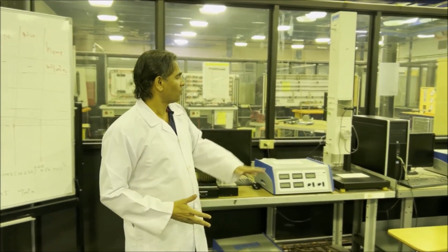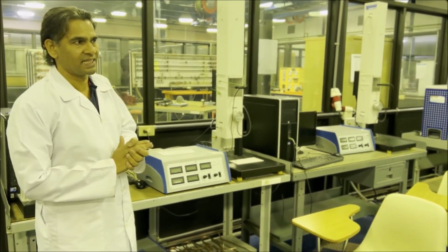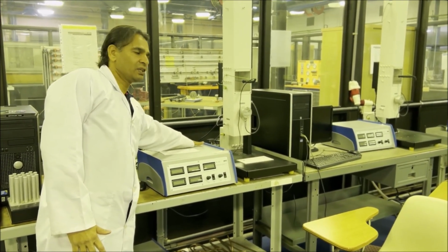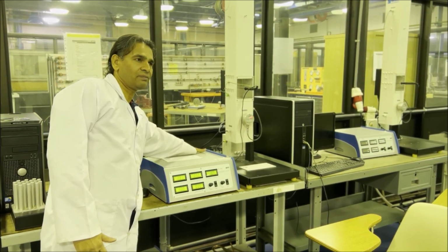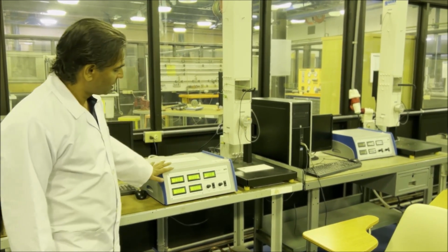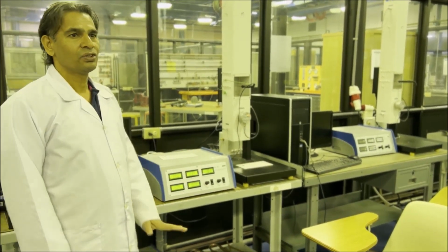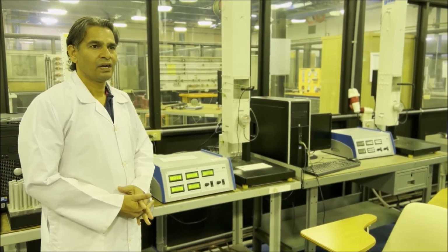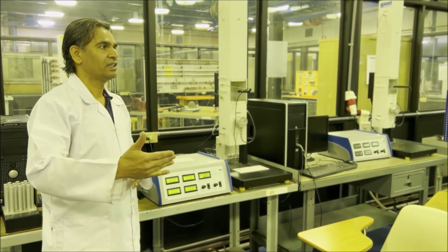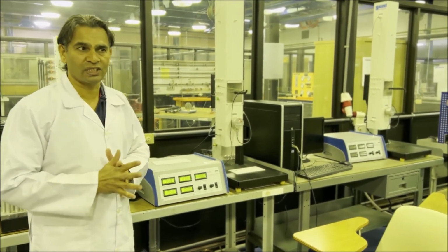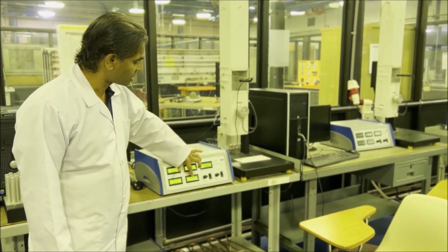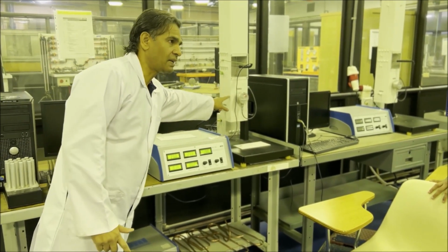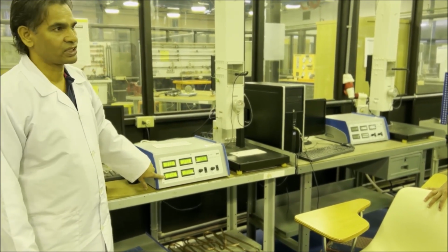Now first we start it and we have to wait for the steady state. There is a black switch, as I explained last week. Make this black switch on. Then we need to adjust the power. In free convection we changed the power, 60, 80, 100. Now here we'll keep the power constant at 80 watt. And we'll start the fan and we can change the velocity.